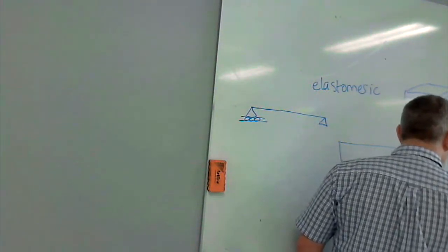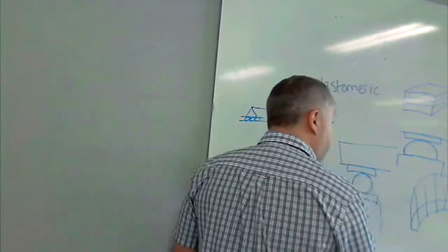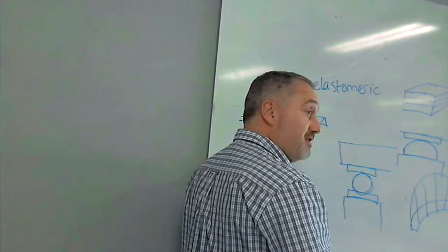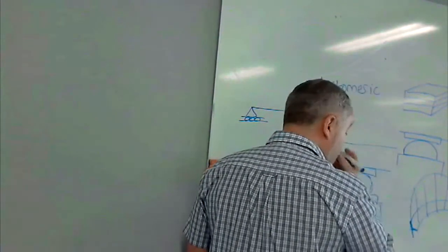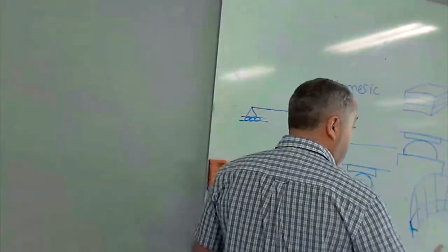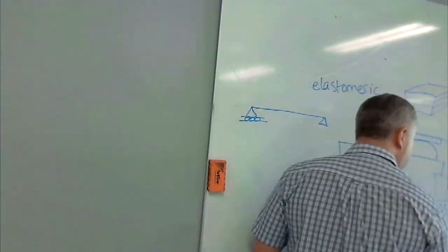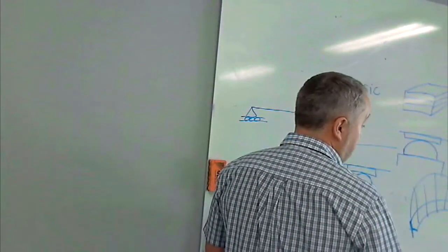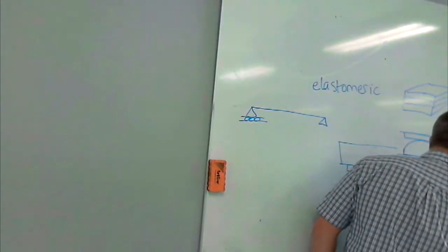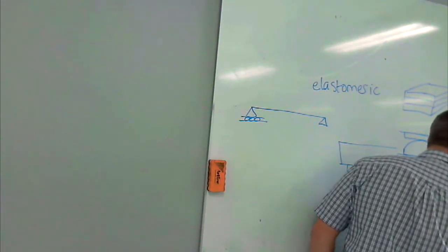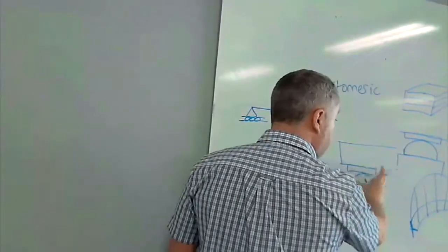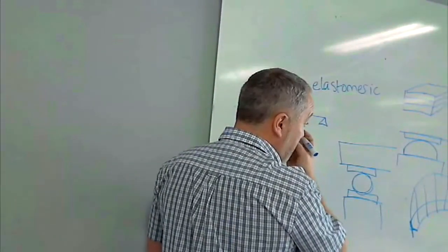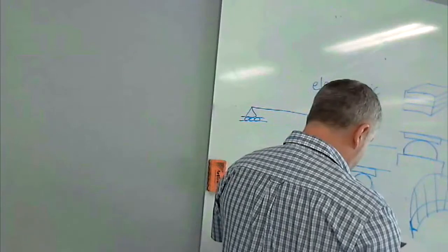The Millennium Bridge. Yeah, my brain's gone dead. That bridge, I believe it's fixed here, so it's actually attached to Gateshead. If the sun shines and it expands, it would push Newcastle away, which is what the Mackems would want. But what you have to do is have some form of a roller, so that if there's any movement, it can just roll slightly. So these are different types of bearings.